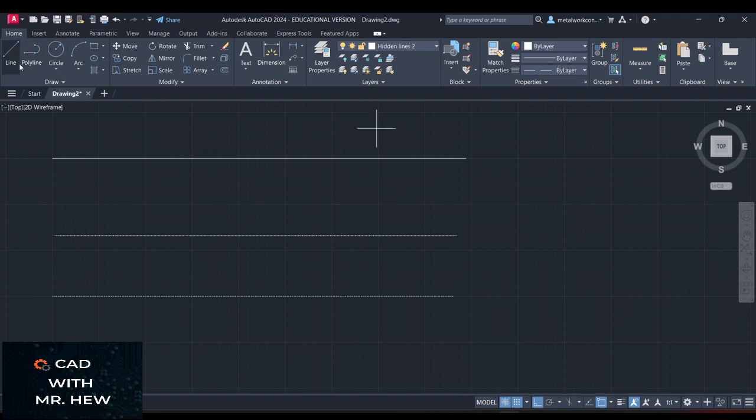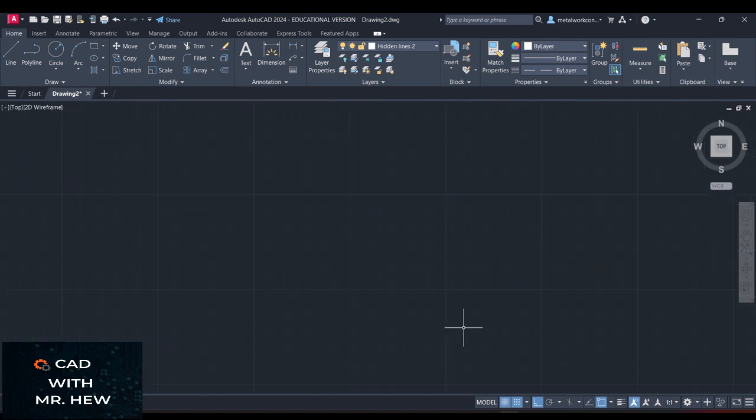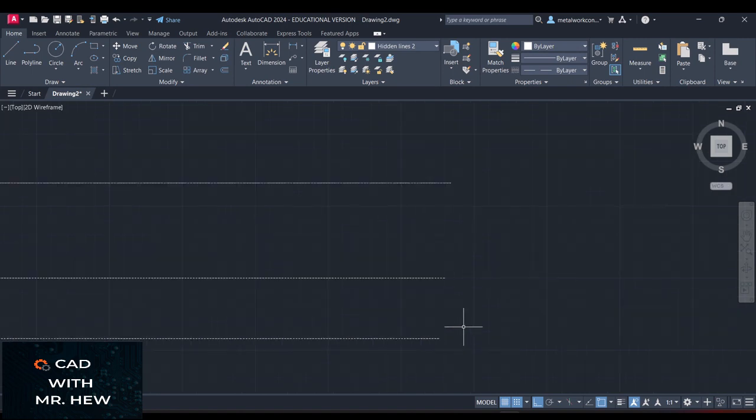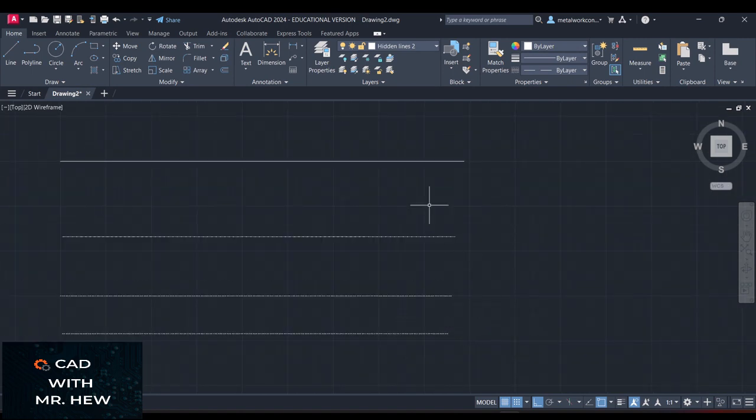All right, so we go line, there, there, enter. All right, we want this spacing to be a little bit different, it's still there, you see? But if I zoom it up, I'm going to load a different one for you. So the first one was a solid line because that was a default line type that was preloaded with the file when we just opened it.